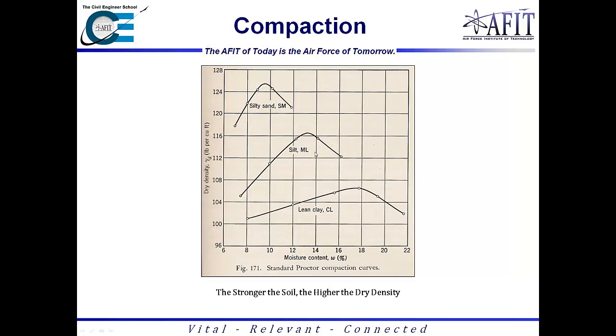And so that's kind of the way the soil profile works. And so if there was ever a conceptual question that indicated the dry unit weight of lean clay was given based on this soil profile and the maximum value was here, if this soil was sandy clay or something like that, where would it plot? And you'd say it's probably higher due to the sand. And so just something to keep in mind.